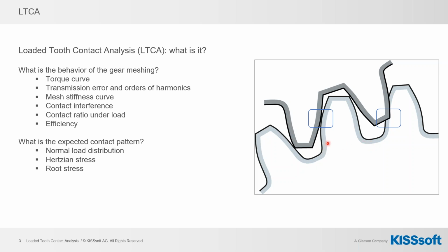And why? Because first of all, the single tooth stiffness consists basically of three components. On one hand, the tooth bending, so the tooth itself is bending. Then the gear body is tilting, so that's basically the tilting of everything that's, roughly speaking, below the root circle.